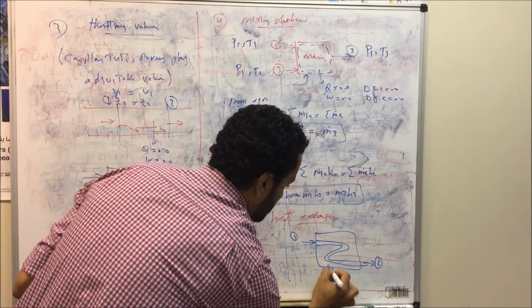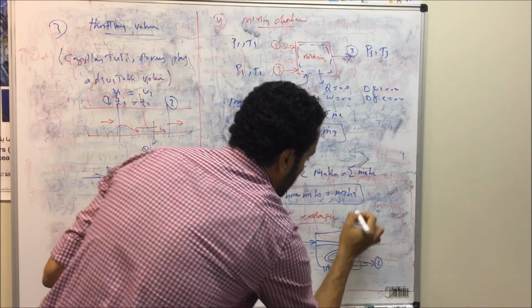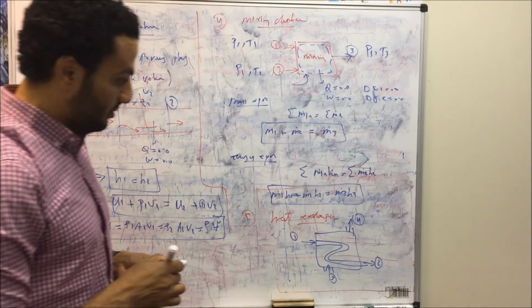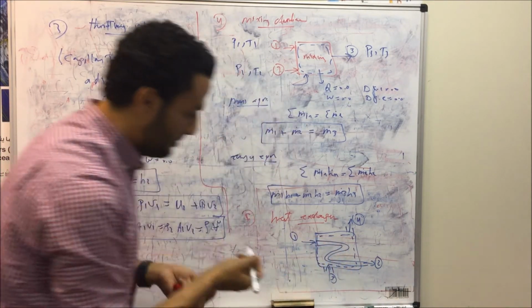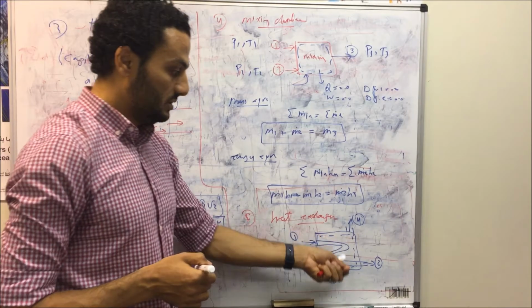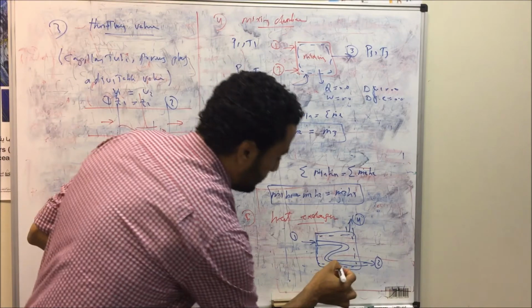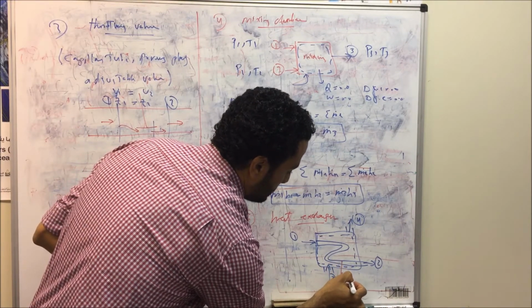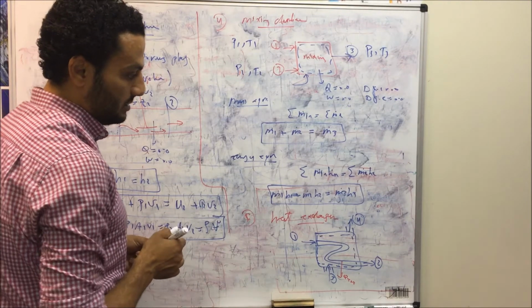And the cold fluid, let's say, on the shell side will be coming at point 3 and leaving at point 4. Usually, if we consider the whole system, we have internal heat transfer from the hot fluid in the tube to the surrounding cold fluid, but externally we don't have heat transfer. This is most probably the case, but we may have heat transfer externally.